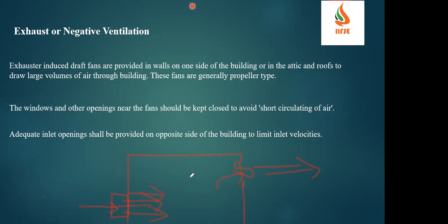So what will happen, in this area the temperature will come down, and even the contaminants get diluted. Even the dust particles will be removed. And also any odor or smell issues in the workplace get removed. Even the humans will feel comfortable because the temperature is in a manageable condition. That's why if you're putting in a fan on the outside, you should have an opening on the opposite side so that the fresh air will come inside.